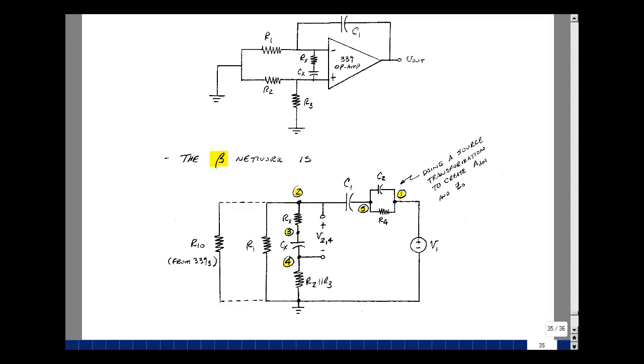Now back over here, this was connected to the bottom comparator that was either an open circuit or a resistor back to ground. And that resistor was R10, that 50K resistor. So I'm going to do the simulation twice, where this is an open circuit and then when it's equal to 50K.